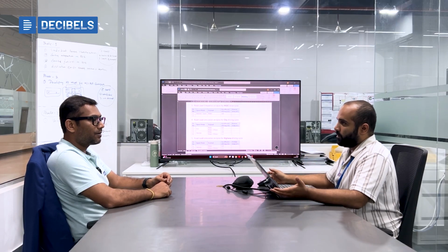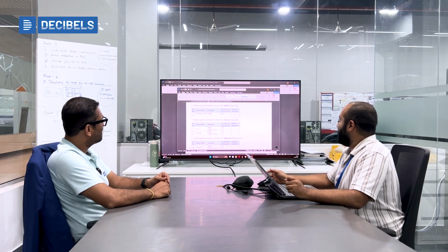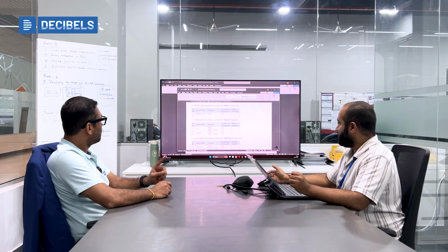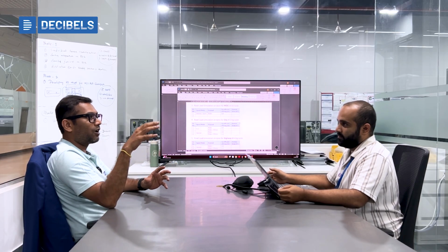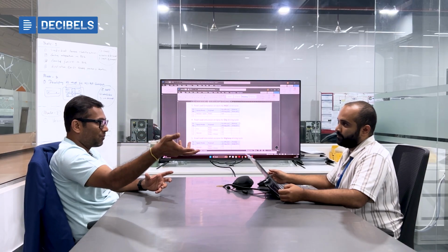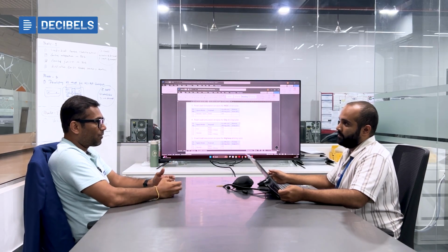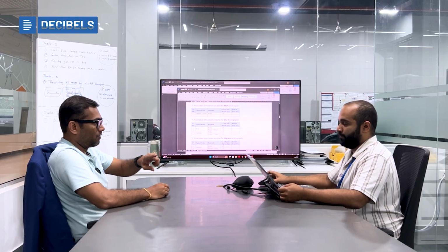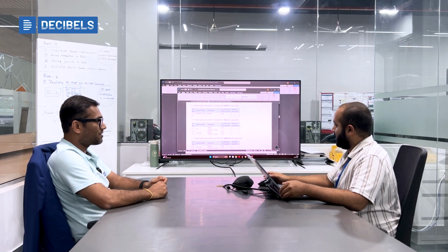Correct. So a person need not even sit on the vehicle to run the drive cycle, because human errors are a lot in this case. That is true, and the number of iterations to get a proper test will also be reduced. When there is no driver sitting in the vehicle, that means we have a closed loop control to control the throttle. Our computational hardware takes care of how much the throttle should be. So that's also a unique component in our dyno, which can do closed loop control to drive the drive cycle test cases.